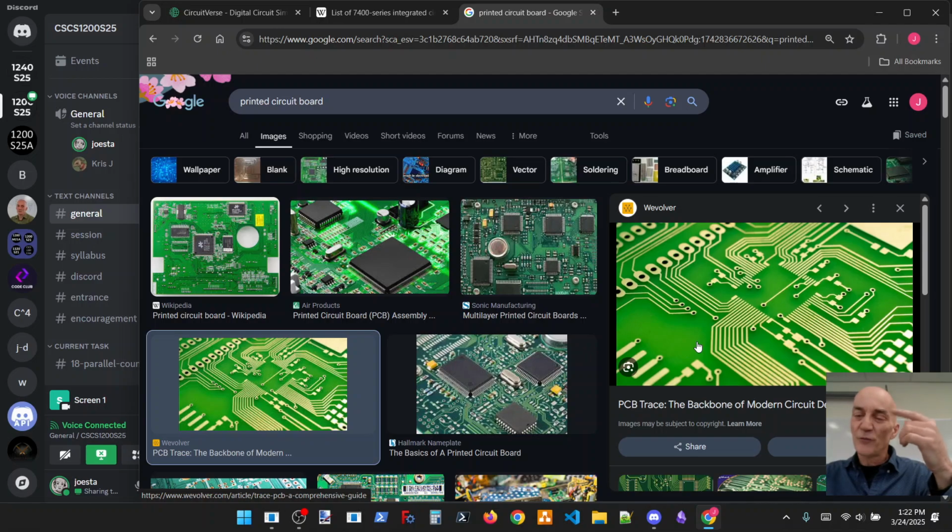Okay. So the difference is welding, we actually melt the base materials, and then they flow together and harden as they cool, and that makes the connection. In soldering, instead of melting the base metals, we're melting a third metal. It flows in between there. So it's more of a soldering or brazing thing.